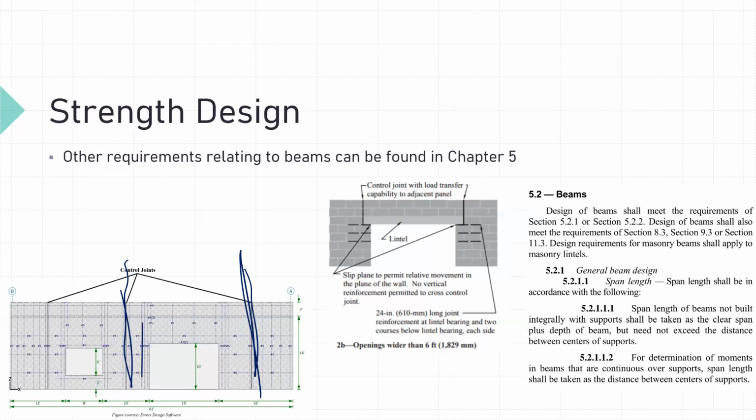So typically a bearing length of 8 inches is used for supports. And because our jambs are typically reinforced with knockout bond beam units, this means that sometimes using a D of 4 inches from the bottom of our unit or of our lintel can be more accurate.